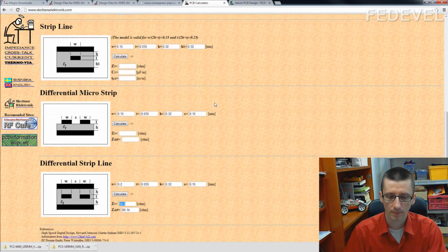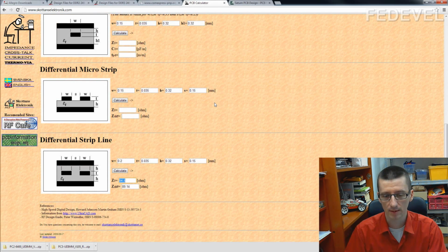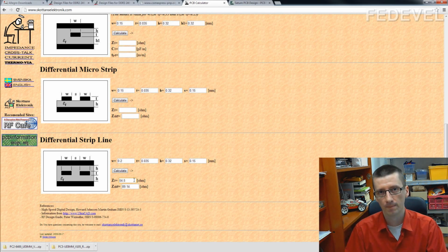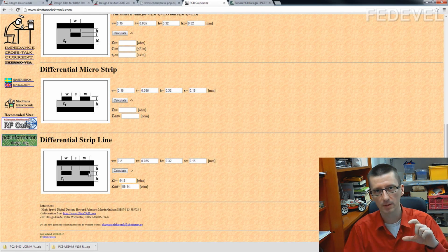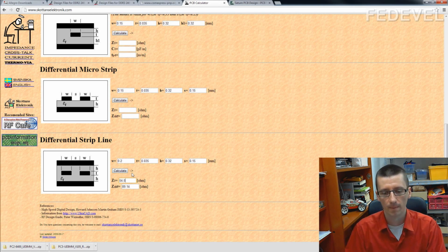It's not difficult, but it may be time consuming sometimes, because when you design your PCB stack up, you need to find the right ratio between your minimum tracks, between what the manufacturer can achieve and manufacture, what your maximum thickness of PCB can be, and what your required dielectric thicknesses are. All this needs to be considered, and sometimes a stack up can be designed very quickly.